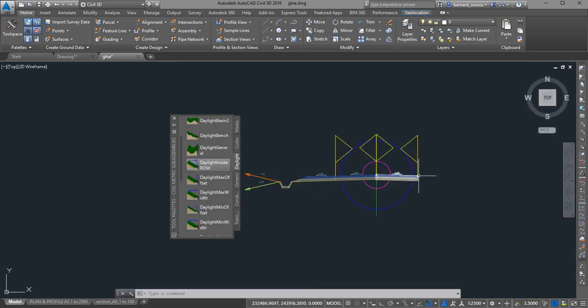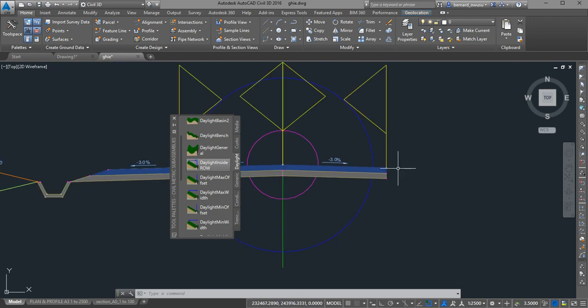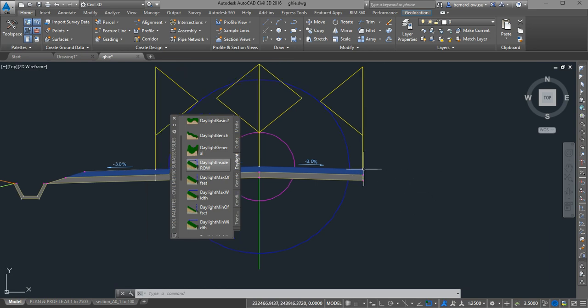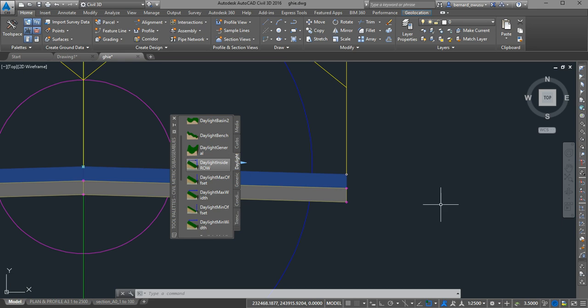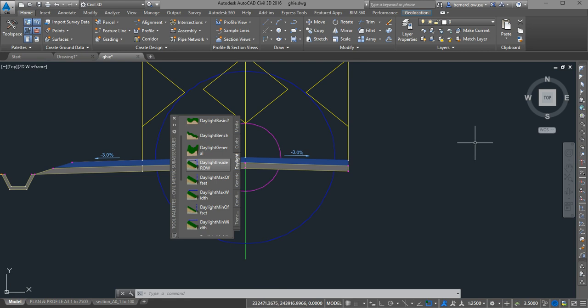We are going to the right. On the right, we'll be having a drain, but the drain is, let's say, under the walkway. So let's continue. We are having a drain somewhere here. So here we are going to have a curb, aren't we? We'll have a curb because it's going to be a raised walk. So we'll put a curb here, then we'll have our shoulder, then our walkway, then you may also have another curb at the end, then we'll have your side slope. Please, are we okay? So let's try and do it.